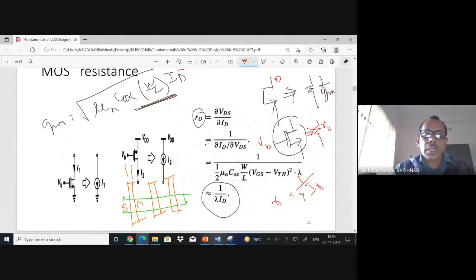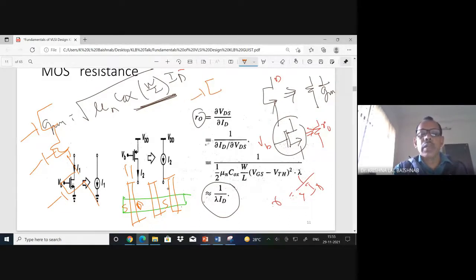Okay. So you see that with polysilicon and polysilicon source drain, I can make source drain. Now, depending upon what combination I want, whether I want MOS in series connection, or MOS in parallel connection. This is series connection. But again, MOS may be connected like this: one MOS here, another MOS connected over here, and both at the same point. So that's another, parallel combination. For a parallel combination, your nomenclature will be different. So that's where we can design the layout and find out the length. This is the length and this is the breadth.